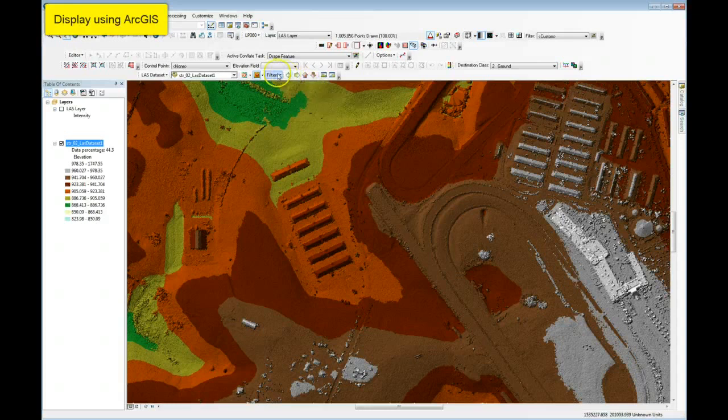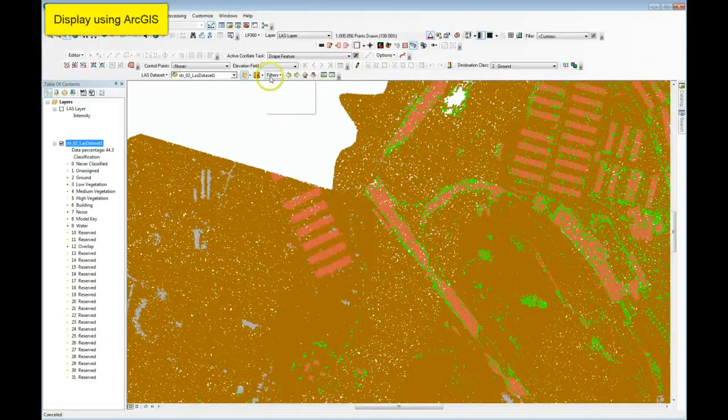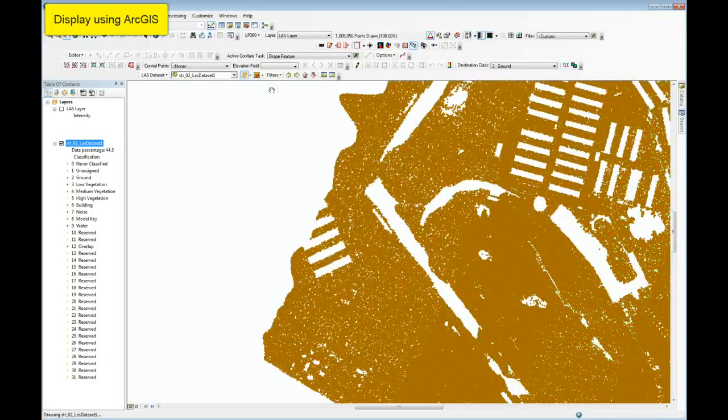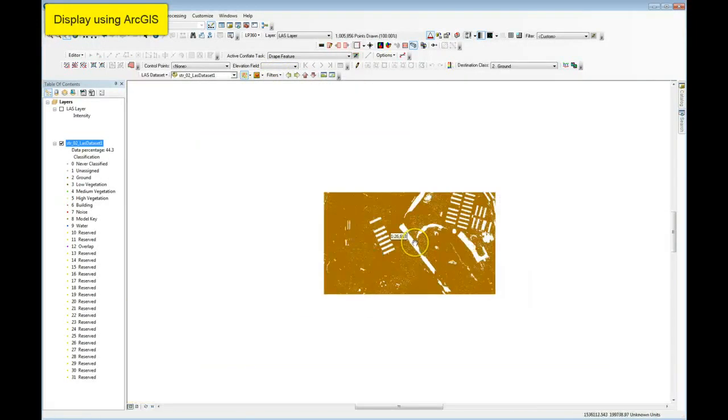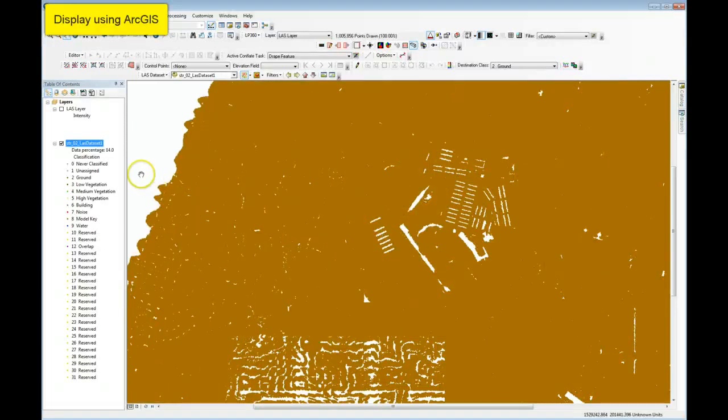The next four controls that I have, or let's not skip over the filters. So filters allow me to just filter by specified classes of LiDAR data when I'm visualizing by class. So we'll switch our LiDAR data back to class, and we can filter by, let's say, ground only. And here we get a view of the ground class. And again, this works fine. If you want to set up other tools within ArcGIS, you can see the classes now displayed. You can go down to the layer properties and put together different class combinations. And of course we have these same sorts of filters in LP360.